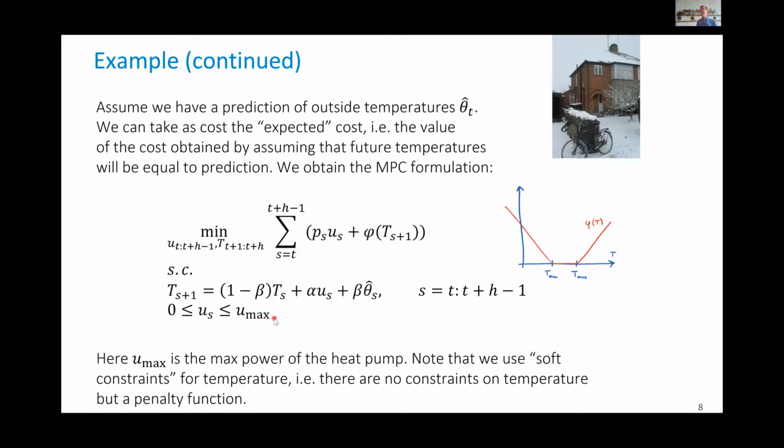Some other heat pumps are less flexible. There may be ramping constraints. There may be discrete values. So you would have more constraints here. And also the constraints are the state equations. So the state at time t+1 is given by those linear equations that capture the thermal model of the house. This is how the temperature will vary when we apply this control. And of course, we need the state because the state here appears in the cost function.